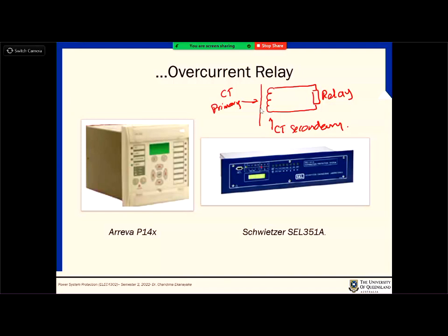Now the primary current creates a certain amount of flux, and it's not a fixed amount of flux, it's changing because you have a 50 hertz current. So it's a variable. And then in the secondary side, now if you keep it open, what happens? The winding tries to push a certain amount of current in the secondary because the primary current is changing.